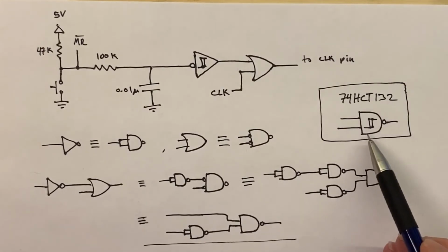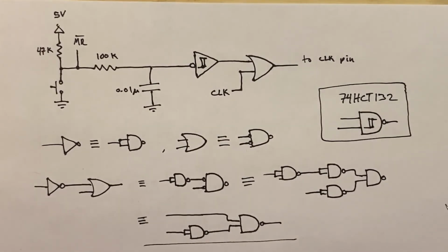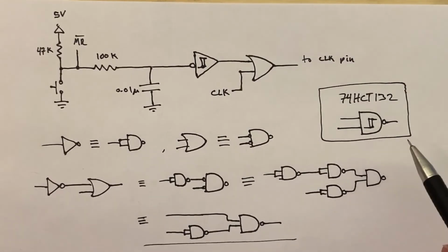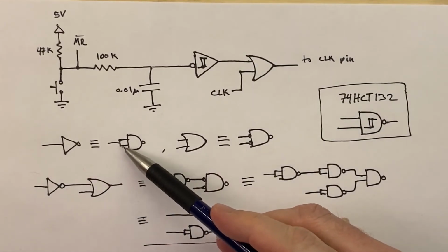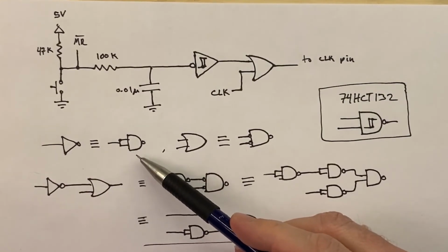Basically it's just a NAND gate with that Schmitt trigger type of functionality. And essentially these NAND gates can be used to make any sort of logic, because if you want a NOT gate, all you have to do is tie the 2 inputs of your NAND gate together, and then it becomes a NOT gate.